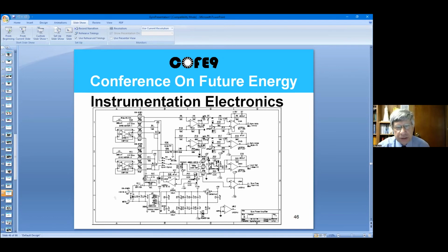In the schematics, you get your 6 volts in here. The power switch goes up and turns the 2 gyros on. It also runs to a DC to DC converter, which powers up the plus and minus 12 volts that runs the electronics. And then we step the plus 12 volts down to 5, because the load cell only takes 5 volts. Then you get up here, you monitor the voltage from the motor. You monitor current through a current sense resistor from the motor, and then you have an infrared pulse counter that monitors the speed of each gyro.